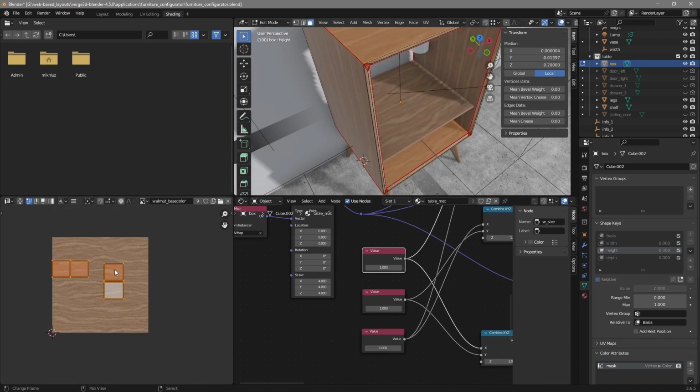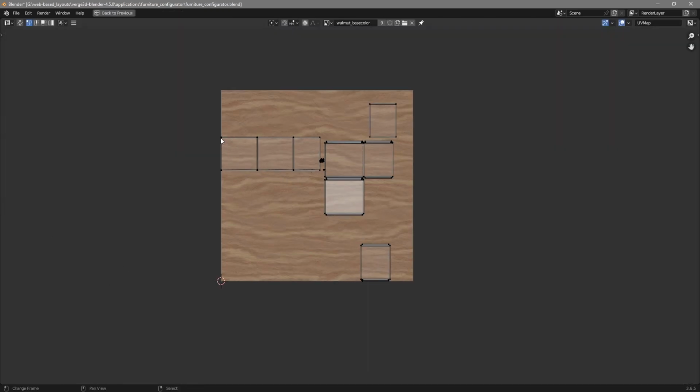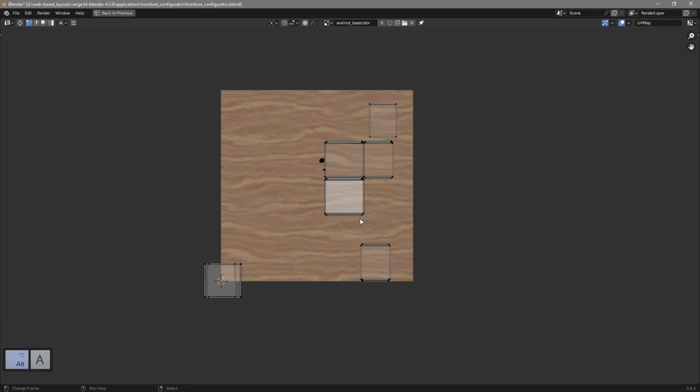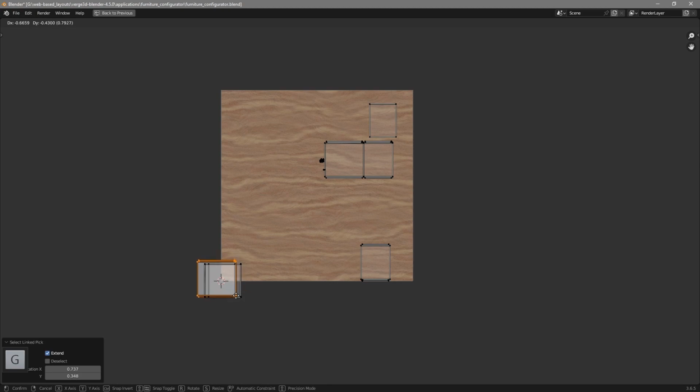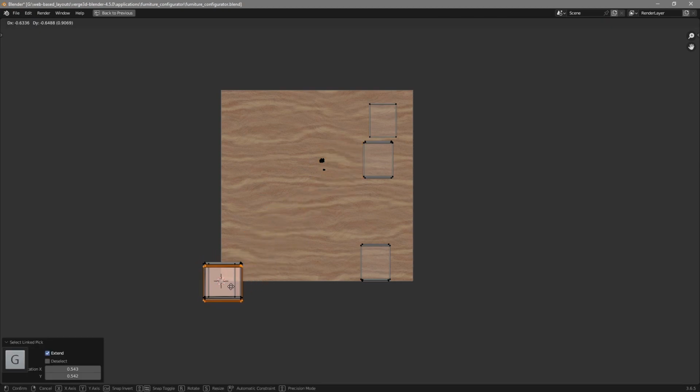And when UV islands are placed away from this corner, when we try to scale the UV, these islands start also moving away from the center, thus the sliding motion. To fix it, we just need to place all our UV islands into the left bottom corner, so the centers of the islands will match the center of coordinates. We can do it approximately, but of course it is better to do it ideally. The better the match, the less sliding we will get.